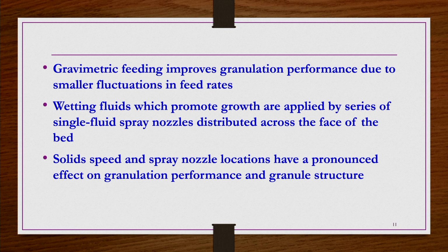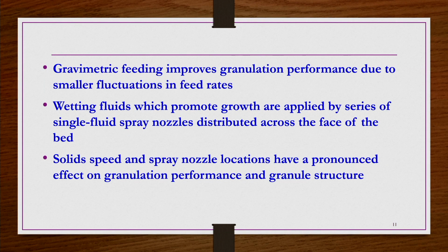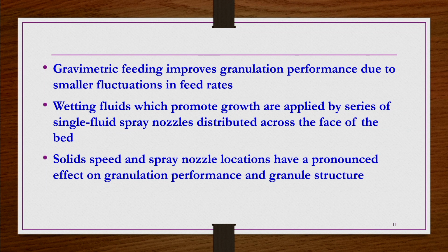Similarly, solids should not come in at a very fast rate, otherwise without being granulated the particles may be leaving the container. And the spray nozzle location should be such that most of the spray is coming into contact with the incoming feed materials to the maximum possible level. So, that is the reason the speed at which solids enter and the location of the spray nozzles used for spraying the binding material both have a very strong effect on the granulation performance and the granule structure produced after the process.